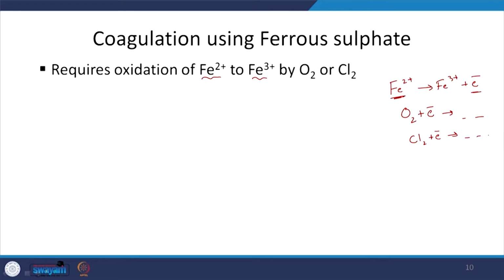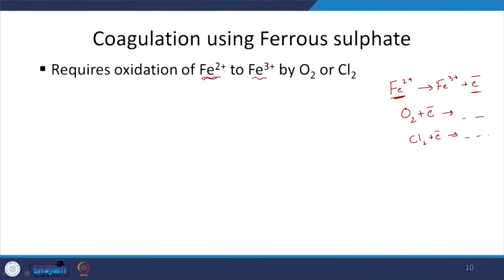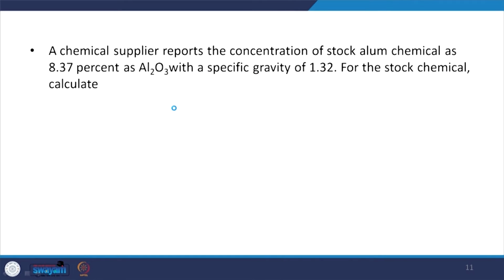So Fe2 plus can be added as Fe2 plus itself, so that it can neutralize the charge. It won't precipitate at almost all usual operating pH and concentration ranges. But if you want to use Fe2 plus as a source of Fe3 plus, obviously you can let it be oxidized by the oxygen or add an oxidizing agent. But again, this is relatively rare, right. So this is what you have, obviously Fe2 plus, and now it is becoming Fe3 plus, right.